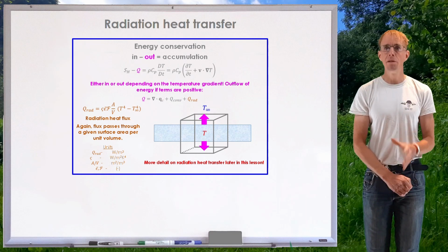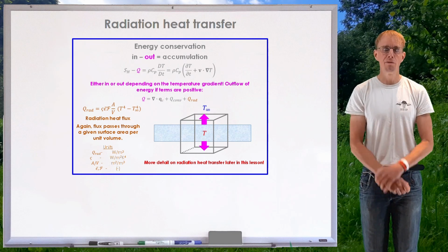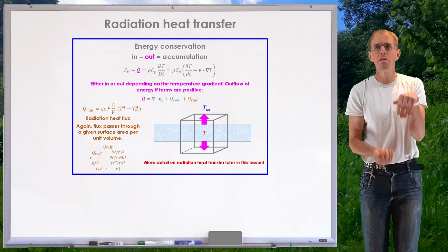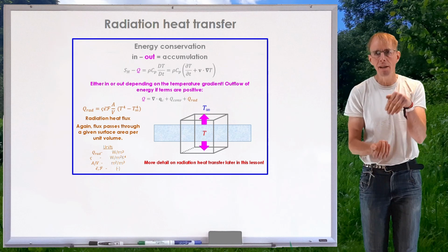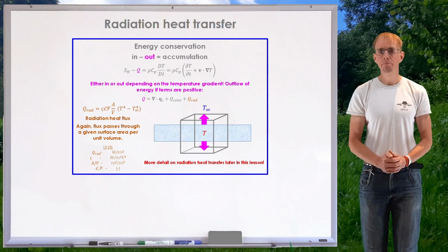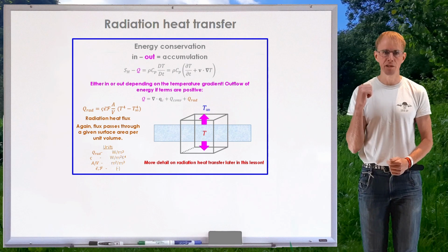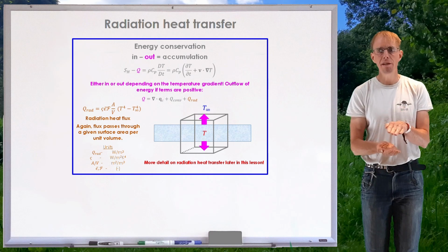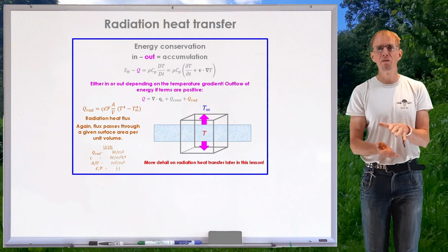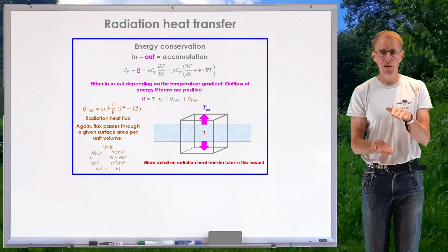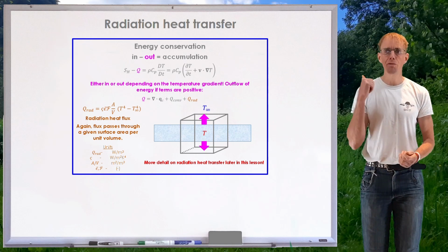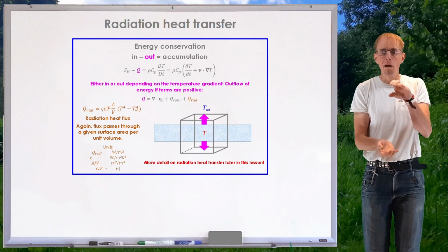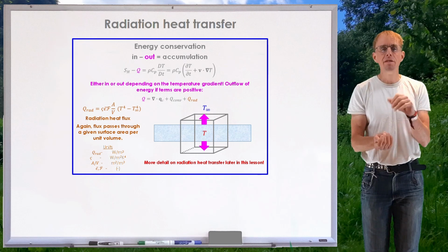And so that is going to be the start point of one of our examinations of radiative heat transfer. That, however, does mean that at that surface all the radiation is absorbed and it doesn't penetrate into the material. So actually, radiation heat transfer features in two places in the energy equation, because if we have a semi-transparent medium, as polymers may be, and all of our radiation isn't absorbed immediately at the surface, radiative heat transfer can also feature in my volumetric energy source term, because radiative energy is being absorbed by the volume of material through the depth of material.